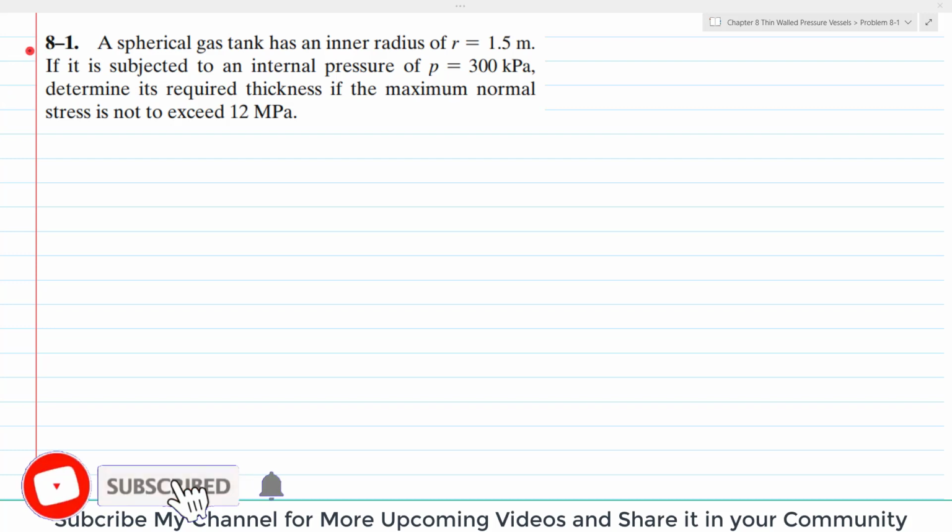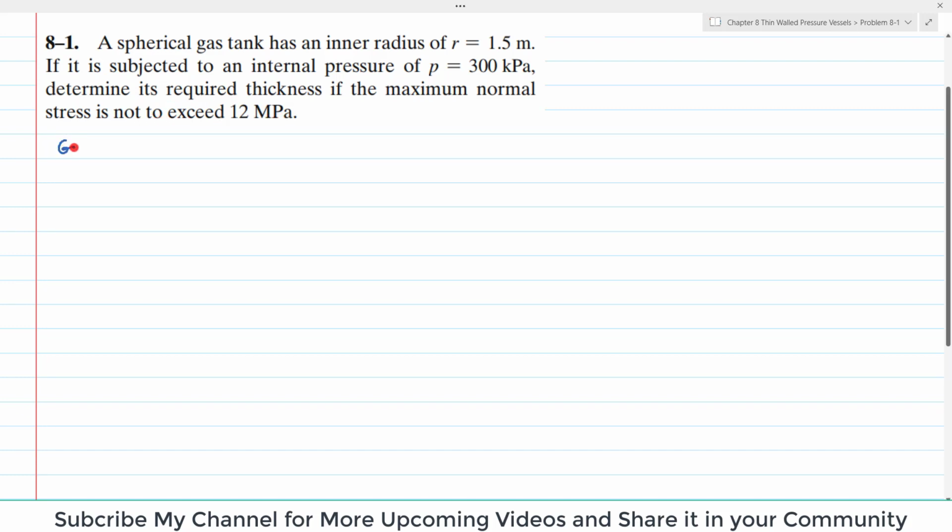Welcome back. Problem 8-1. The statement is: a spherical gas tank has an inner radius of 1.5 meter. If it is subjected to an internal pressure of 300 kilopascal, determine its required thickness if maximum normal stress is not to exceed 12 megapascal. So let's start with the given data.